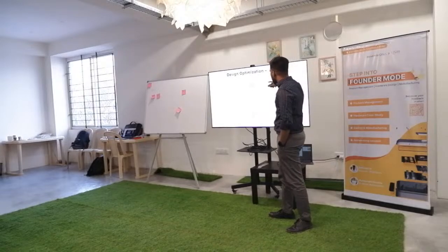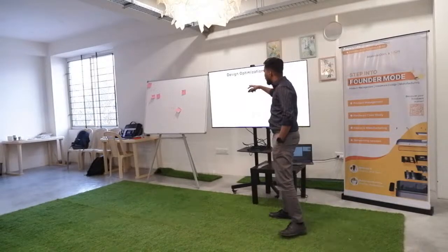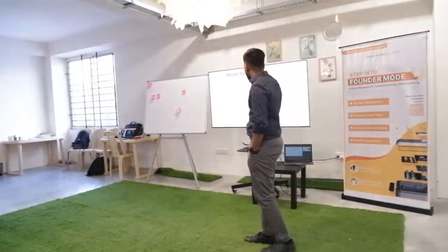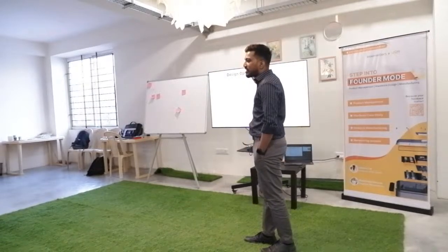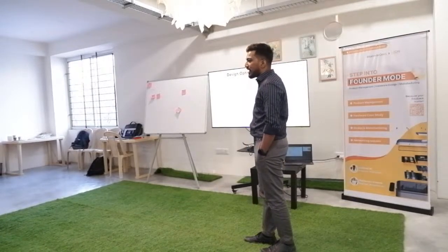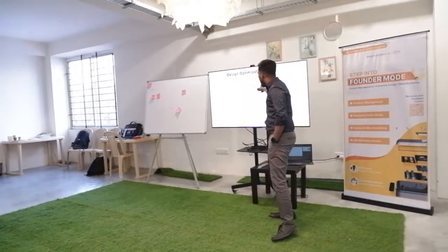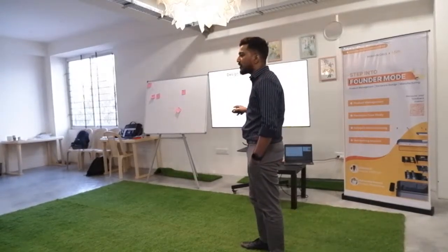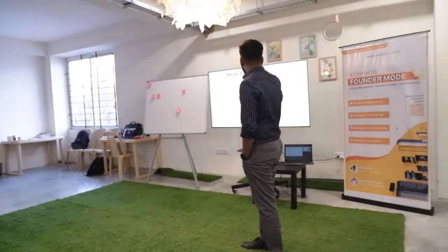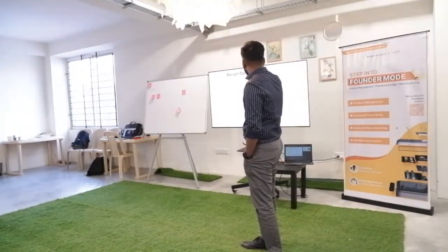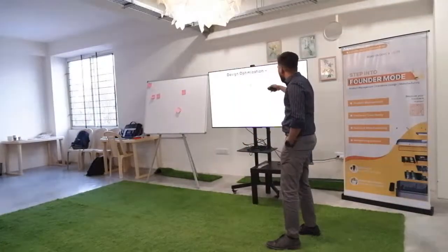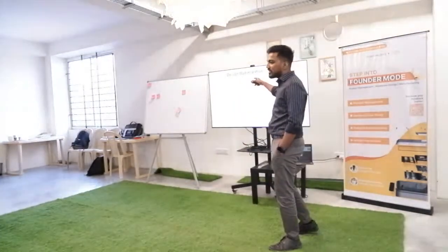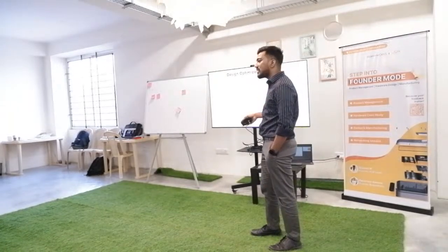And here the main thing you can observe is there is something called a 5.1K resistor. That resistor is used throughout the circuit everywhere, but it is not the best option that we have. It was supposed to be used only for the USB. That is the USB-C standard where we have to use a 5.1K resistor and pull it down. And the same resistor I would have used in multiple places. For example, I would have used it for the LEDs also. I would have used it for the switch, but it's not recommended. But the thing is, even if it's not recommended, it works.